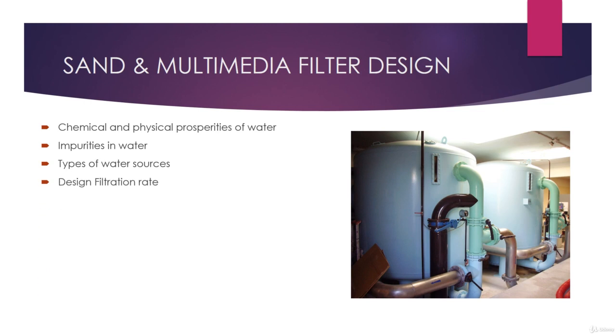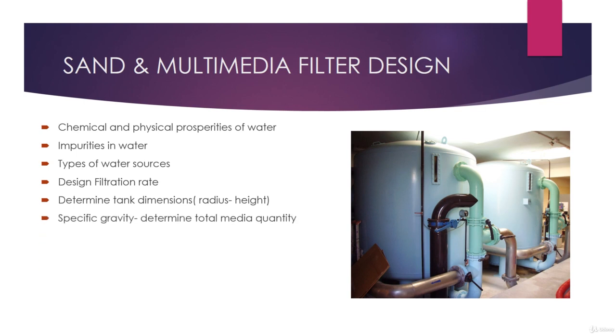Then we will start learning the steps of designing sand and multimedia filters. We will learn what is the importance of the filtration rate and how it can be calculated and determined, and we will calculate the dimensions of the filter, its diameter and height, and the other specifications of the filter vessel or tank. We will learn what is the relationship between the filtration media layers depth and the media grain size of each of these layers and the importance of this relationship in determining the quality of the water produced and the cost of installing the filter.